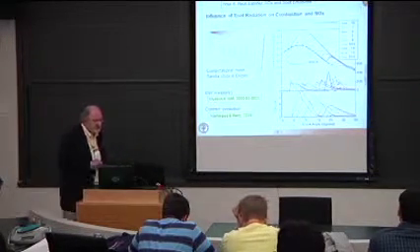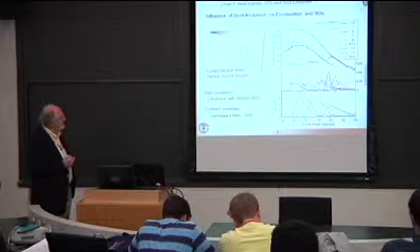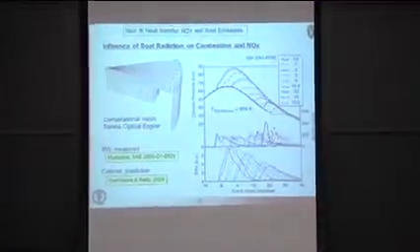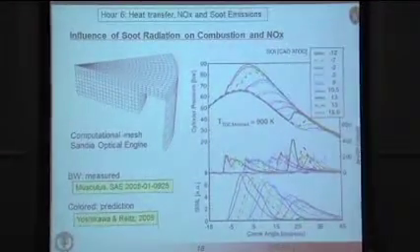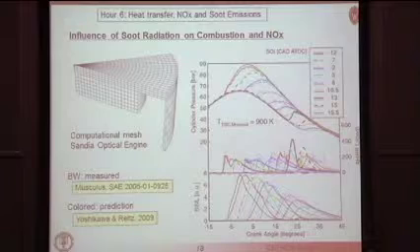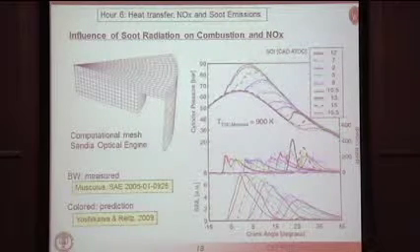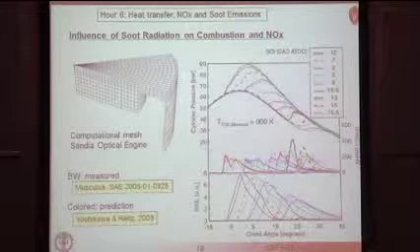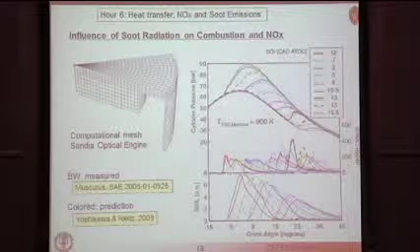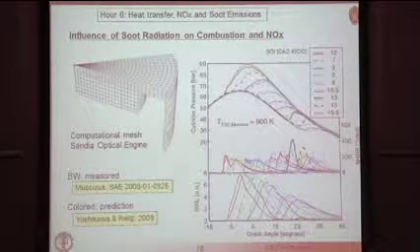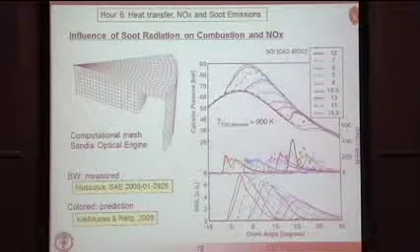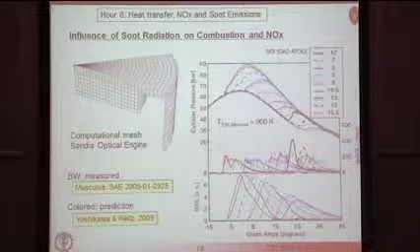So let's finish up by talking about soot. First thing is, how important is soot? We already discussed, when we discussed the radiative transfer equation, that radiation is important and that a significant component of the radiation comes from the soot. Mark Musculus at Sandia did some interesting experiments in his optical engine where he essentially changed the start of injection timing and measured the heat release rate and pressure traces, as you can see here. And then on the next slide, I'll show you the corresponding NOx measurements.